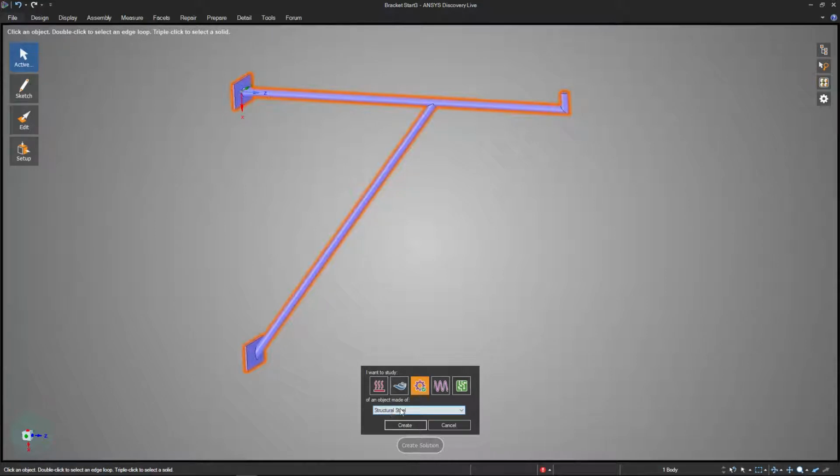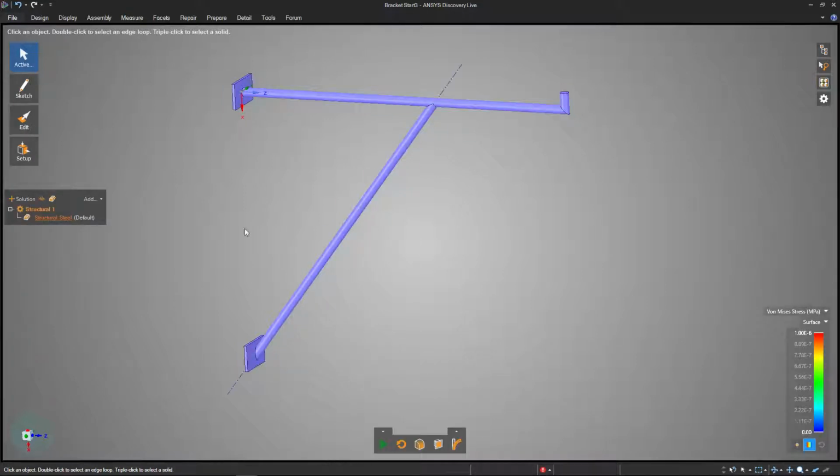We'll look at how to adjust some of the properties of this to make it perhaps match the actual material you have a little bit better. All right, we'll go ahead and create that. Nothing exciting happens except getting a few more boxes on the screen here. The reason for that is every solution, regardless of the type, needs a few boundary conditions defined. For a stress analysis here, we need to know what's actually being held in space so that it can't move, and then where's the force. Without those two things, it can't give us any meaningful information back.